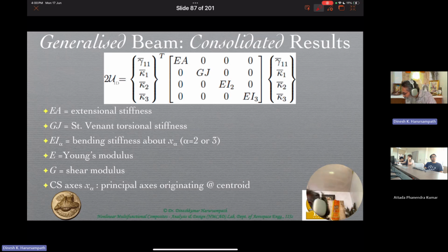But in general, you would have a situation like this where here the chord is much more, here the chord is much less, the thickness is much less here, the thickness is much more over here. So there is a taper essentially, right? You could also have multiple sweeps, as in this case. Till here you have one sweep angle, here you have a different sweep angle. It may not be evident from the leading edge, but from the trailing edge you can see it, because what is important is the line of the mean aerodynamic centers. So you would have all those kinds of changes in the geometry, in the material, etc., along the length.